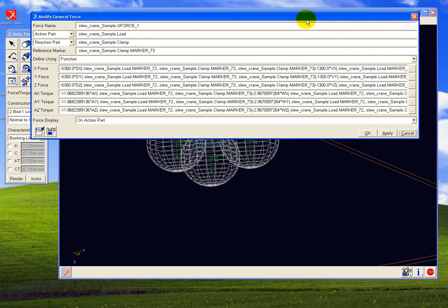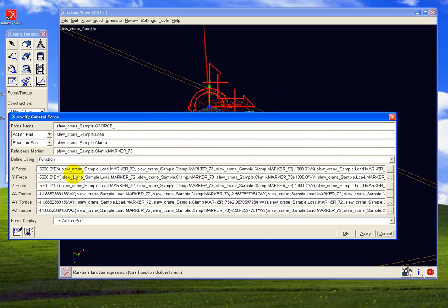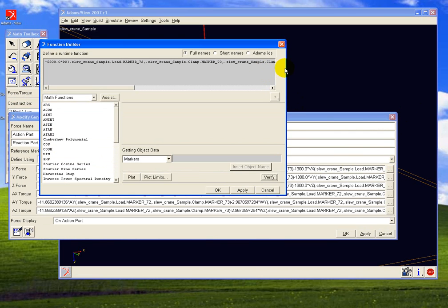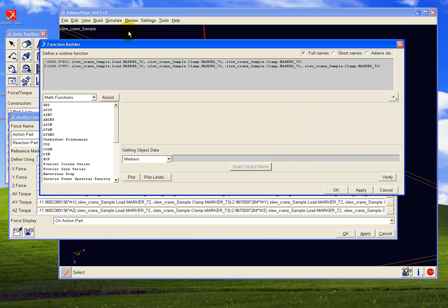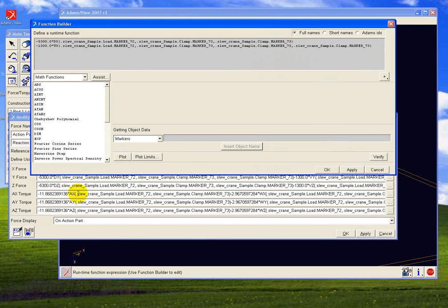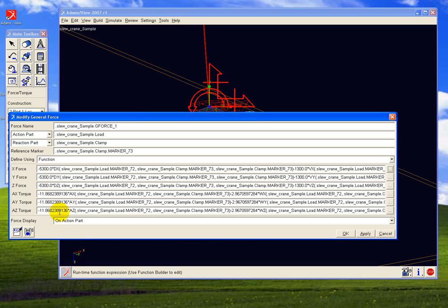Now you can have a look at the components in the force. Don't get confused now, but basically this is nothing more and nothing less than 6 linear spring damper forces connecting the 3 directions and 3 rotations relative between the 2 end parts. So basically what you have here are the equations to define these 6 springs and dampers. If you would now be able to switch those forces off, switch those springs off, you would be able to really grasp an object and then release it at a certain desired point.